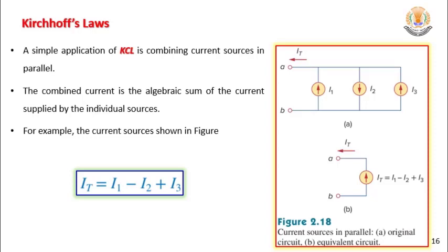All of them can be replaced by one current source up. So I have to follow those up first, so they can be replaced by I1 plus I3 minus I2. If I reverse the direction of the equivalent current source, I have to start with the one which is similar, down. You understand?